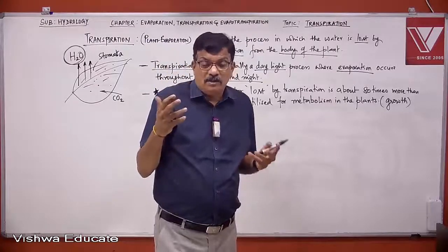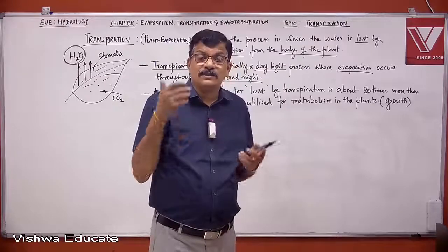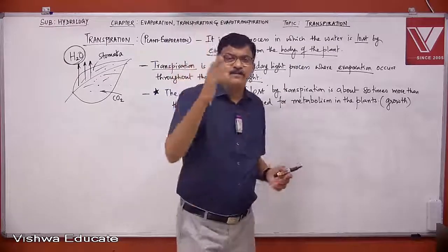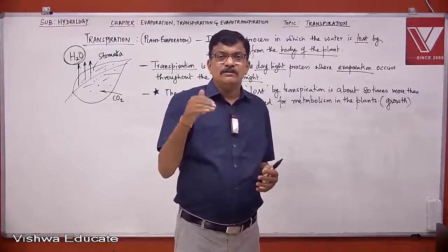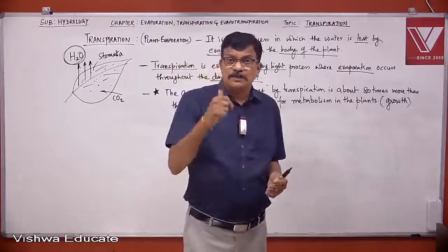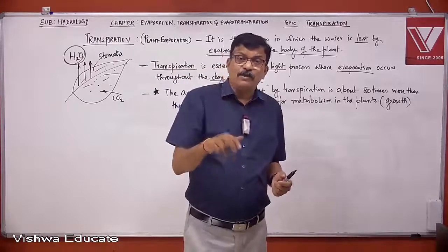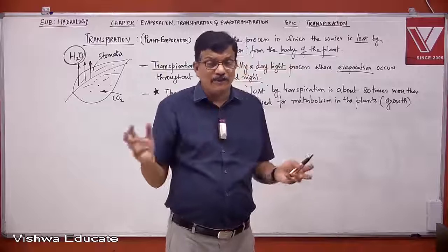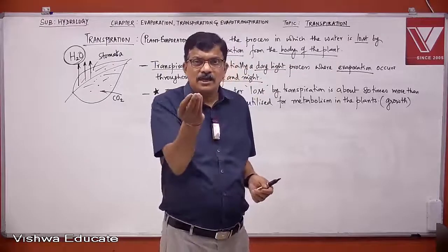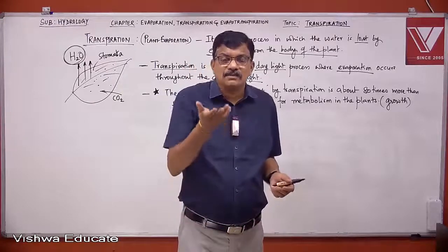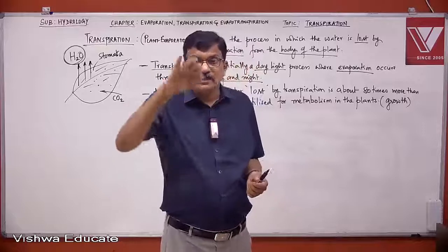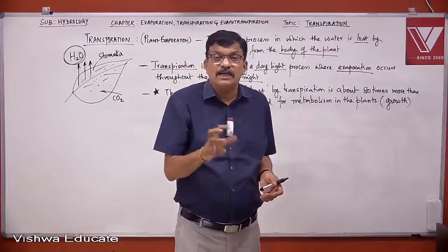Partly there are a lot of losses, runoff losses, seepage losses. There are so many losses, which you will also discuss in the irrigation subject. But whatever water is consumed by the plant after all these losses, hardly about 20% is actually consumed for metabolism. The remaining 80% is lost to the atmosphere by diffusion.